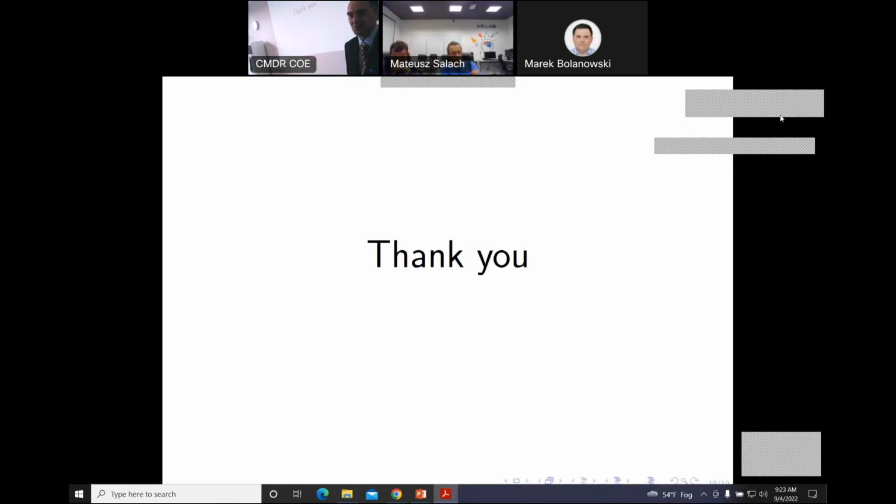So our system has no garbage collector, because a control system doesn't like to grow and to shrink. So our system is fixed. Also this previous one was written in the order of the ST standard, which was described in IEC 61131 standard. Thank you very much.